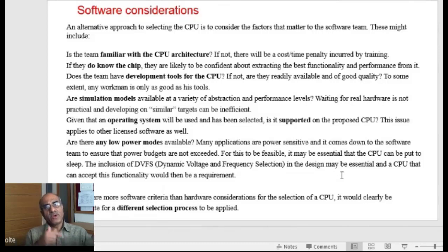So depending upon what type of algorithm you need. For example, you have one algorithm where you are writing code for 16 bit and 32 bit, and you are switching between this 32 bit and 16 bit. So 32 bit for your main program and 16 bit only for sending data to the IO devices, isn't it? You are sending data to and getting data from that IO, so that you can work within your whole program that might be 32 bit.